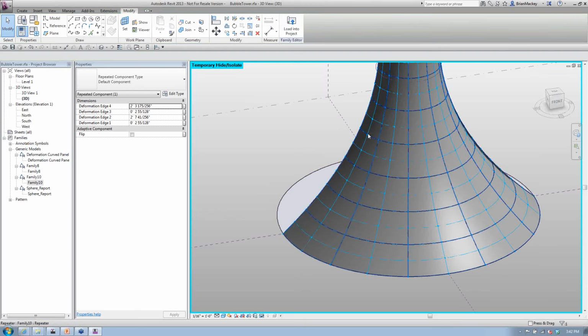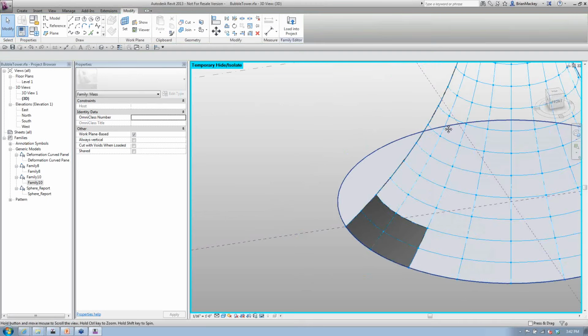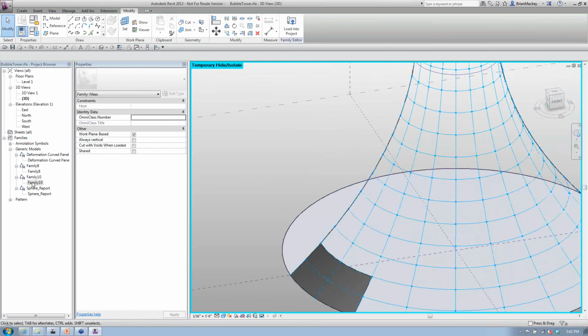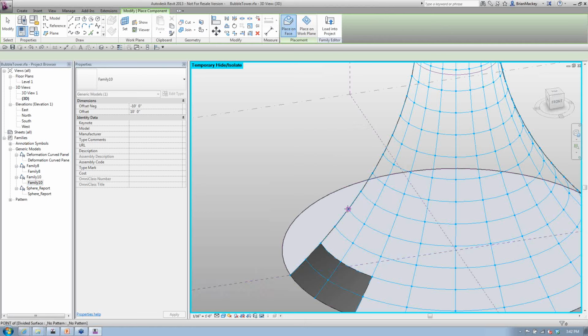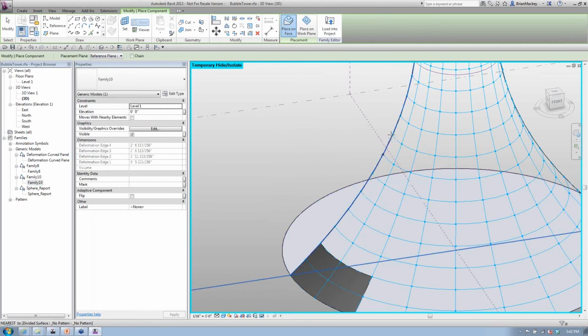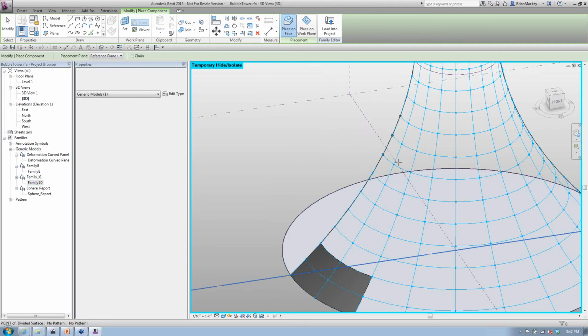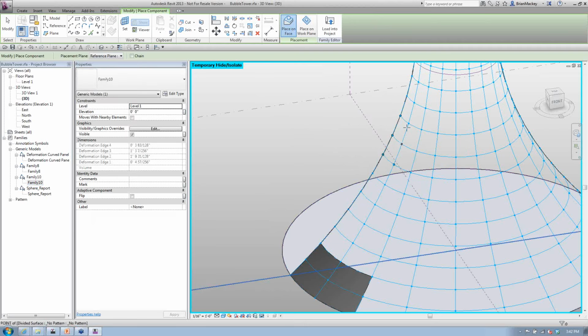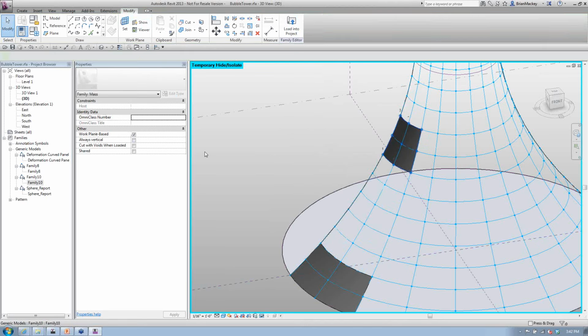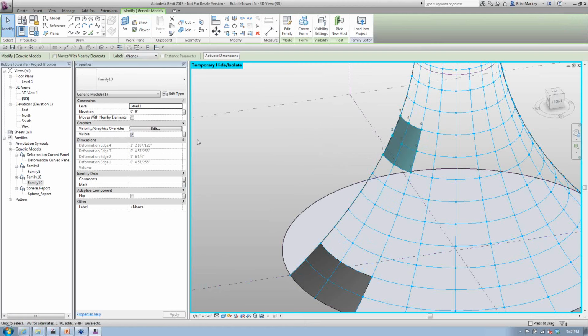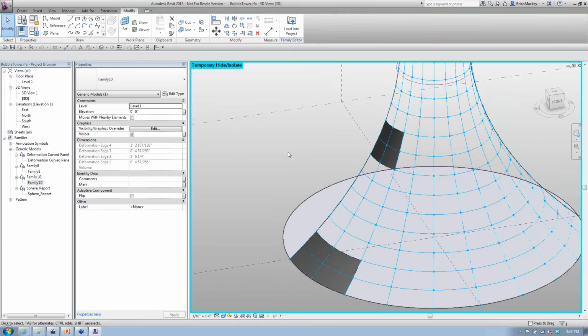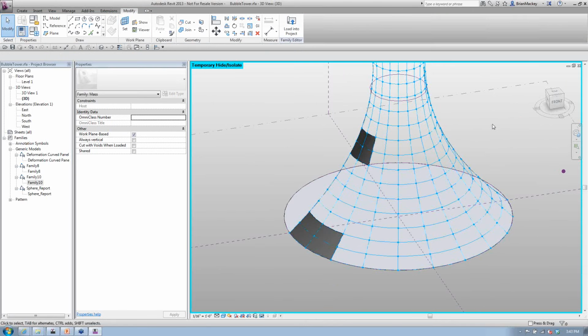Yet if I go in later and put it in up here manually, I guarantee it's going to be some different numbers. So just a heads up on this, if you are doing it, 3, 2, 3, we'll just do it up here in the middle. If I come up here and do it on this one, I'm going to get different numbers. So it's something that I've asked a couple people on. I haven't formally submitted a request yet. And they were kind of like, we haven't noticed it, so I don't know if it's something that I do. But anytime I use a repeater, it gives me the same value on my reporting parameters. So I wanted to give a heads up on that, let people know that is an issue. So if you're really getting into this and you need to do every panel size, you might have to go through and do each one individually.